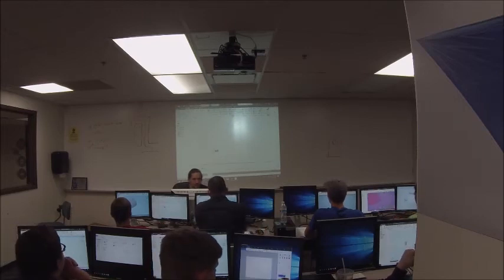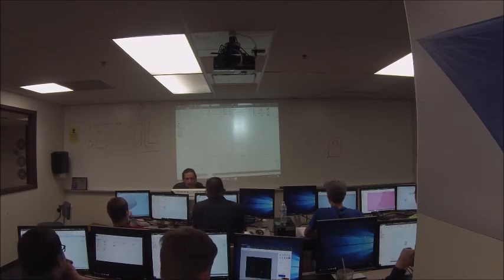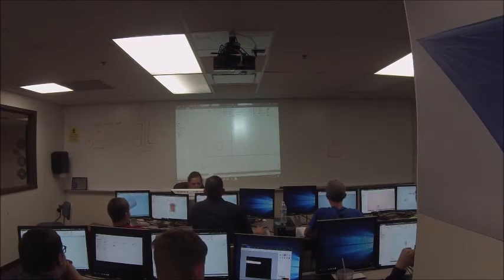I can add a circle, right? I can dimension that circle to the edge of this part. I want it 1 inch, maybe 1/2 inch off the bottom. It'll let me place the dimension. There we go, 1/2 inch off the bottom. Make it 1/2 inch in diameter.